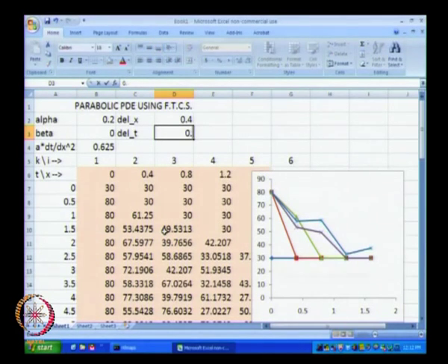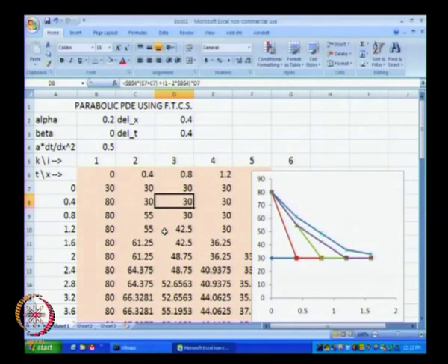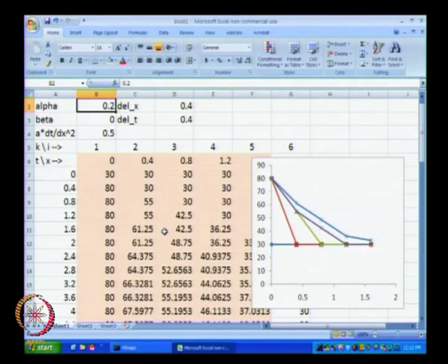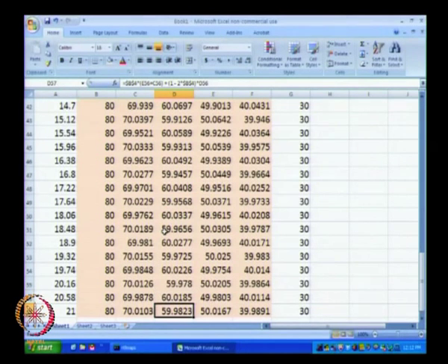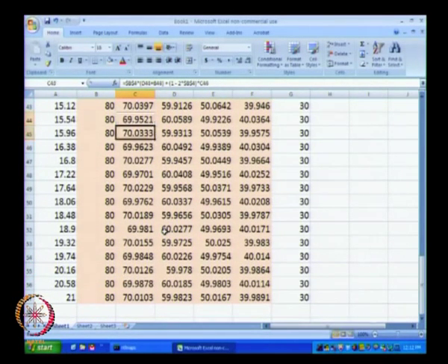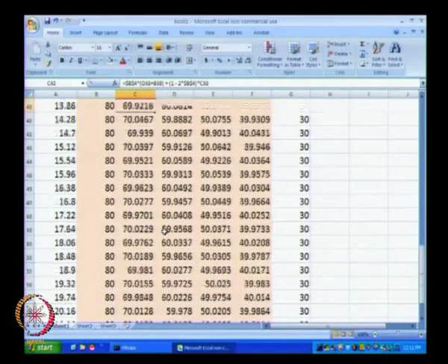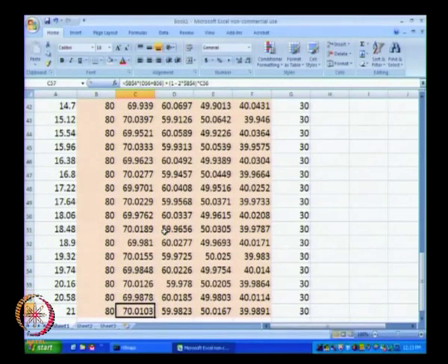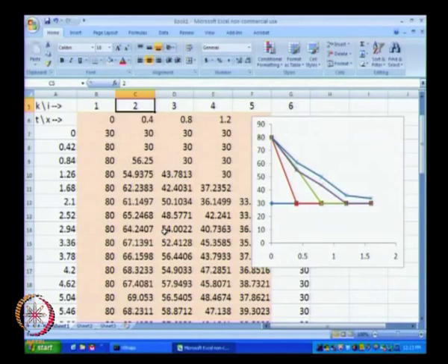And what happens when the delta t is kept at exactly equal to 0.4, we will get the temperature to be stable. Okay. The temperatures are not unstable, but the temperatures are indeed stable when delta t is 0.4. What happens when we go to 0.42 is we will get some kind of oscillations, if you see over here, and if we go to long enough time you will see that the temperatures indeed are tending to diverge and not converge. We started with temperatures of 56 initially, and then they are going to 70, and they are hovering around 69 and 70, so on and so forth.